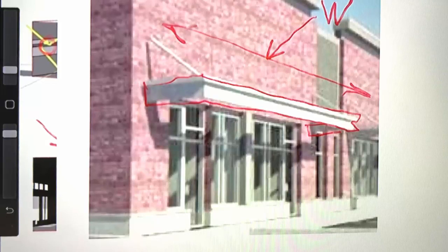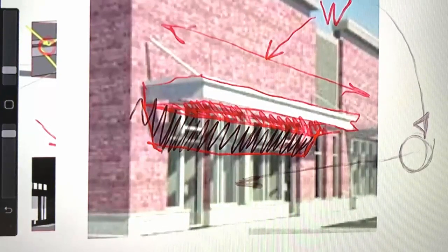western sun, while any solution in terms of canopies will not be as effective, because even if it was opaque, let's say this was a slab of some sort, the rest would still be there. And the sun goes down that way, so it becomes too horizontal in the west, that this kind of canopy will not be viable to protect the space from this kind of orientation.